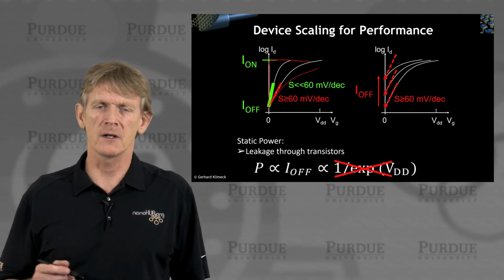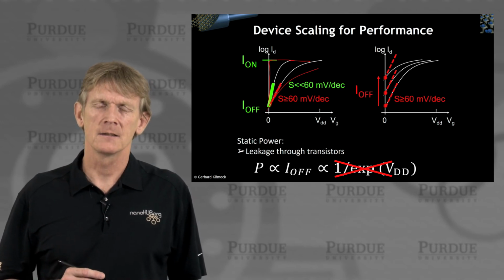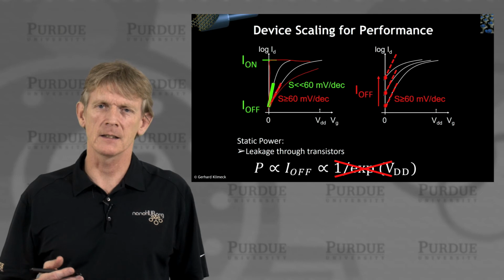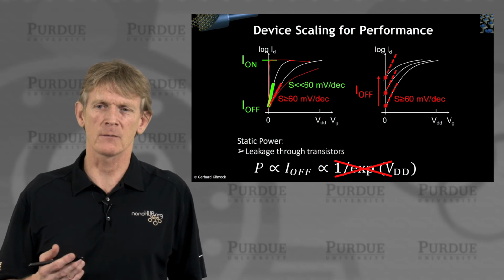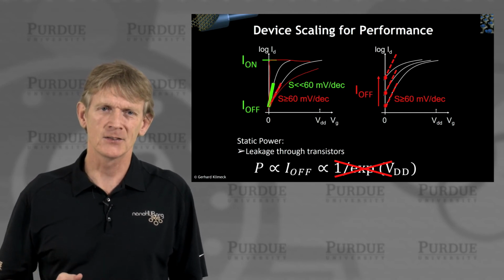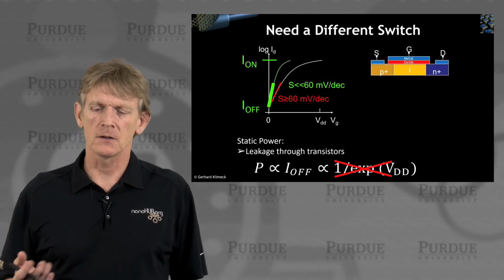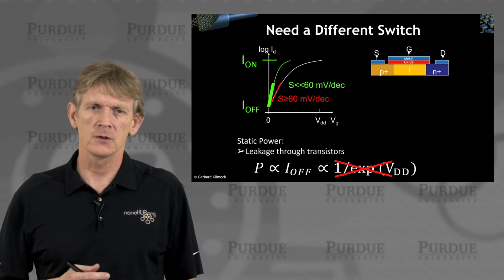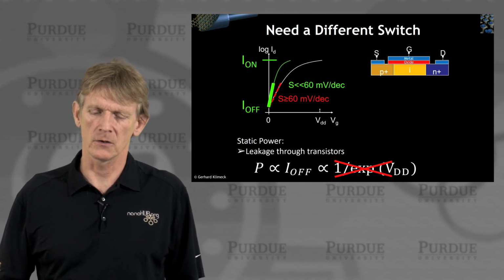So there's a whole field of device engineers and researchers like me that have been hunting for a switch that has this characteristic. And you have to now understand what are the fundamentals of this 60 millivolt per decade, and can you overcome that with some trick? Or if you apply this trick multiple times, then it becomes a method, right? So what might be one of the candidates? Well, the fundamentals of the normal CMOS you now understand. Now I'm going to sketch for you one potential alternative that might reduce your leakage current.